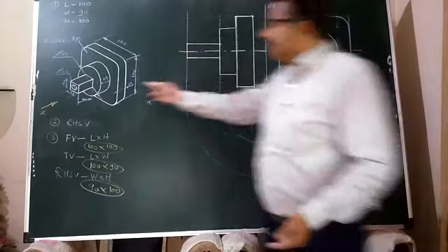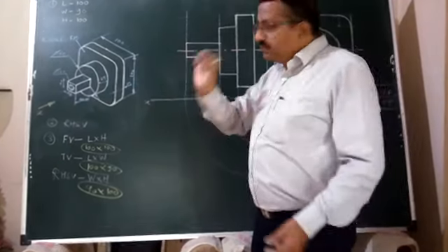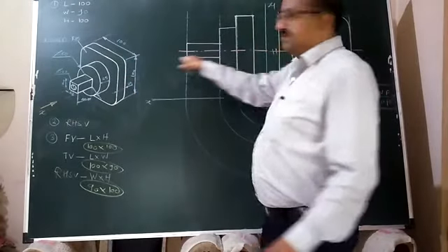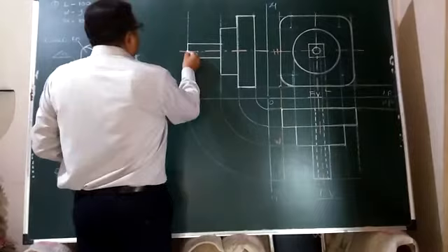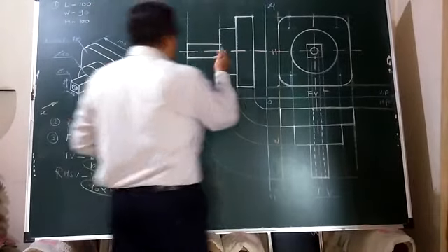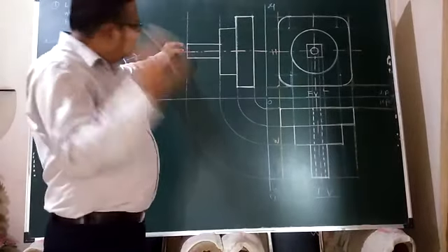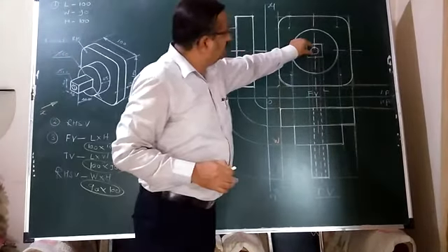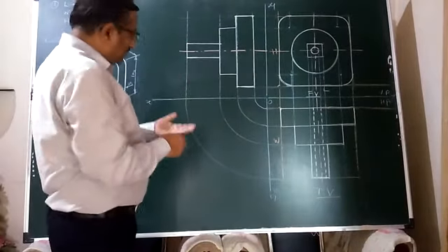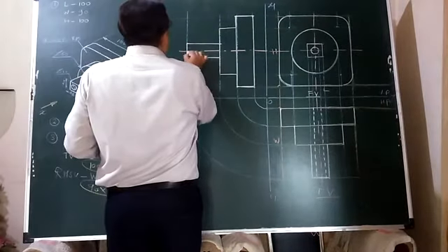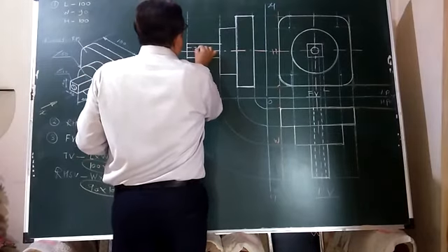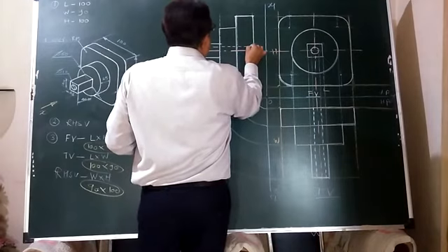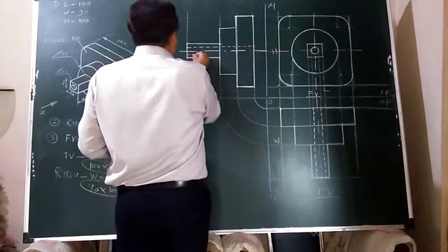Similarly, inside also, as it is not visible to the observer, one should show the dotted effect or dash medium thick line effect. Horizontally, it should run throughout this object. 10 mm is its diameter, so naturally 5 mm above this, 5 mm below this, either mark by scale or projection lines will help you. You can mark these points and now just go on producing those dash medium thick lines throughout the width of the object, left extreme edge to right extreme edge.